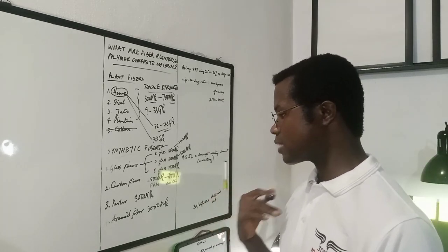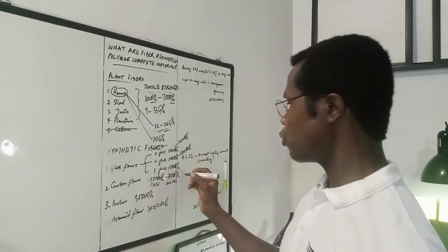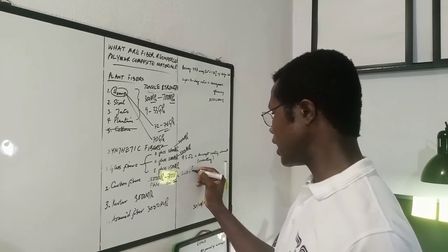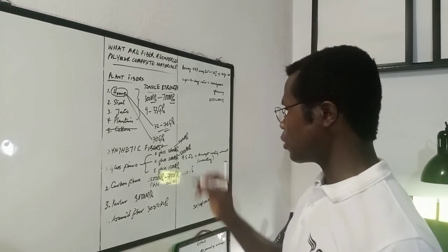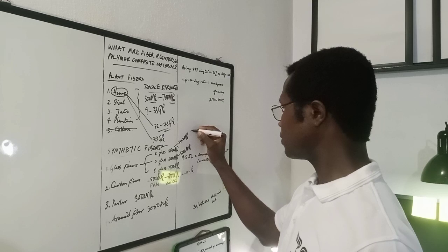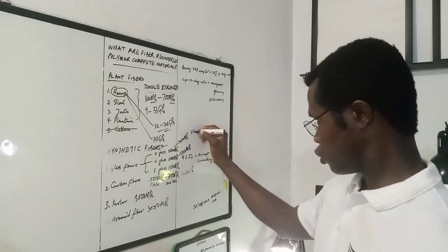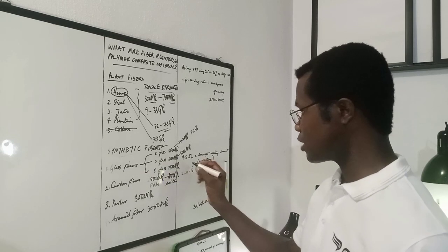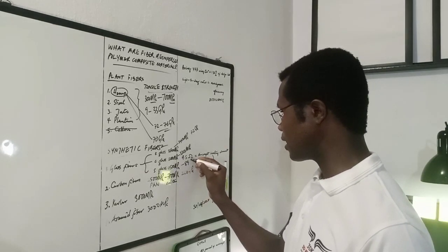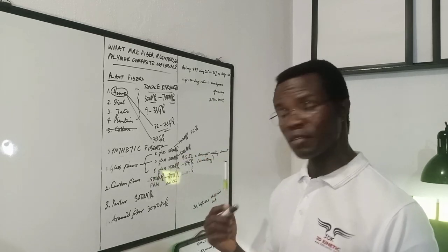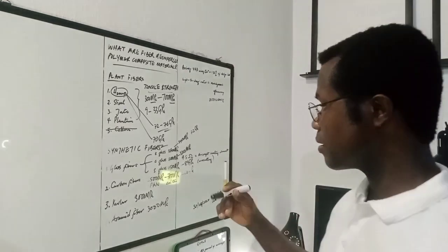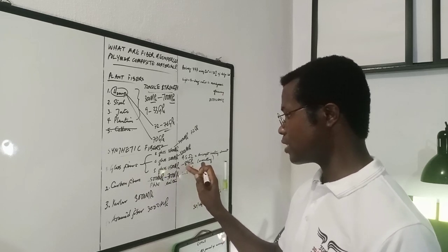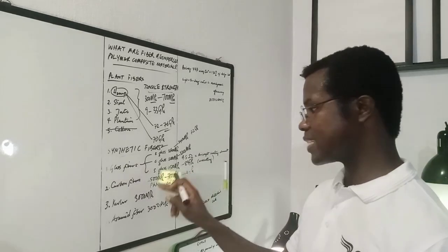For modulus, the stiffness, carbon fibers rule the pack. The highest modulus you have is up to 260 GPa, gigapascals, for carbon fibers. For E-glass fibers, you have up to 72 GPa, I think I mentioned this before. For S-glass, you can have up to 89 gigapascals for the stiffness. You can see that these are very impressive materials. With S-glass in particular, you have not only a very high stiffness, you also have a very high tensile strength, and it's not as expensive as carbon fibers.